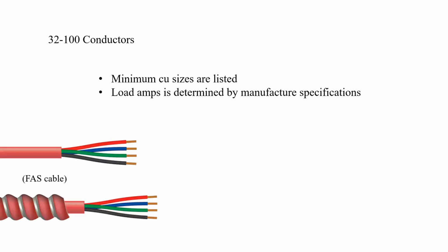The rules for fire alarm within the CEC are not specifically for the location or specific arrangement of components. Rather, they're very general in nature and a general overview of the requirements when it comes to conductors, raceways, and power supplies. 32100 covers the installation or the types of conductors. Notice they're all of copper and that they must be capable of carrying the load current.